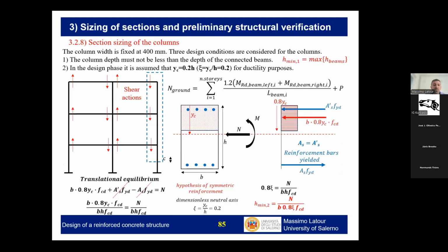For the columns, basically, let's take the shear and estimate the axial forces in the columns. Basically, what we can do initially is to magnify the action in the columns to account for the self-weight of the elements, so the self-weight of the column and so on.